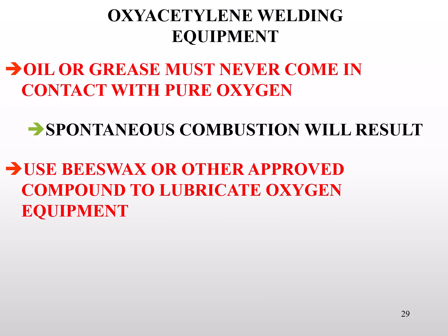Any time you're handling oxygen, whether it's welding oxygen or aviators breathing oxygen, you should only use clean tools, free of oil or grease. The reason is oxygen itself does not burn, but it makes any fuel that it comes in contact with very susceptible to just ignite. Because of that, all tools, equipment, even our hands and clothes should be free of grease and oil.